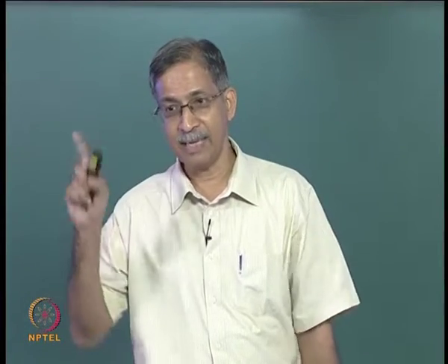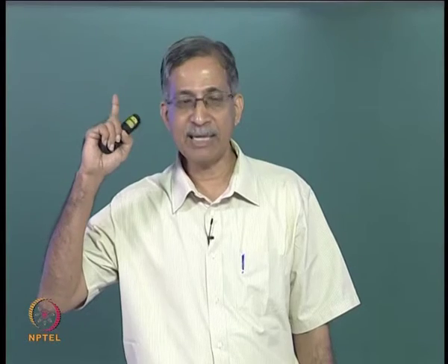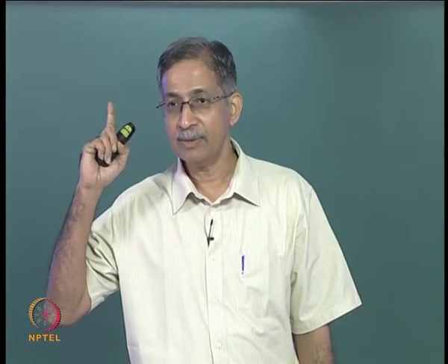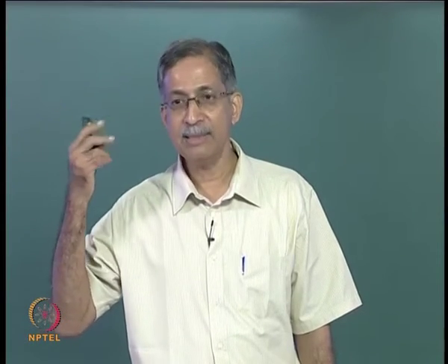So are you comfortable with flexibility method? In your examination, I will ask you at the most only trusses, because whenever you have intermediate loading and all that, flexibility method is not good. So this you just read and put aside, do not break your head too much over this, but trusses you should handle any flexibility problem. Is it clear? Two types of problems, direct loading, second is lack of fit or temperature loading. Can you handle those two?